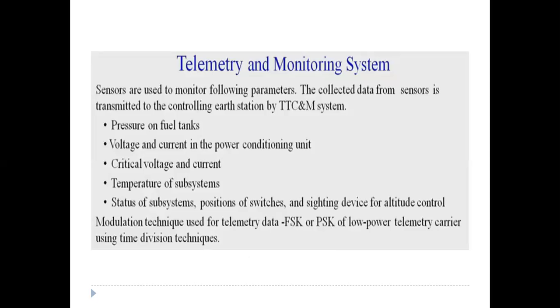A low data rate is normally used to allow the receiver at the Earth station to have a narrow bandwidth and thus maintain a high carrier to noise ratio. The entire TDM frame may contain thousands of bits of data and take several seconds to transmit.